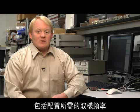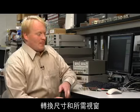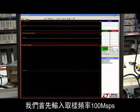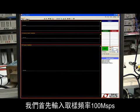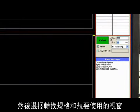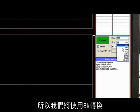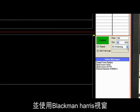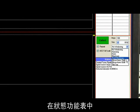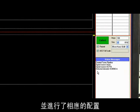PScope needs to be configured with the desired sample rate, transform size, and desired window. We first enter the frequency which we are sampling at, 100 megasamples per second. Then we select the transform size and window we wish to use. We will be using an 8K transform, and since we will not be using coherent sampling, we will need to use a Blackman-Harris window. In the status menu, you can see that PScope automatically finds and configures the demo board accordingly.